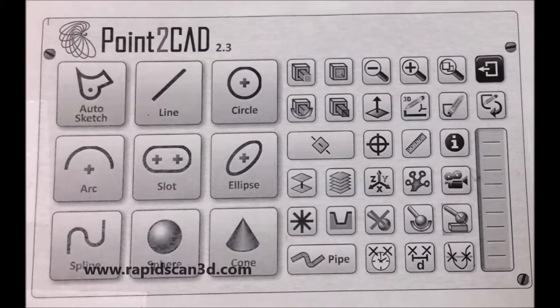This is the command plate that the CMM machine utilizes in its plug-in software Point2CAD inside of Solidworks. The command plate allows you to draw circles, make sketches, arches, as well as create features with those sketches such as extruding and cutting. It allows you to also orientate your sketch drawing as well as create planes and different reference geometries as needed.